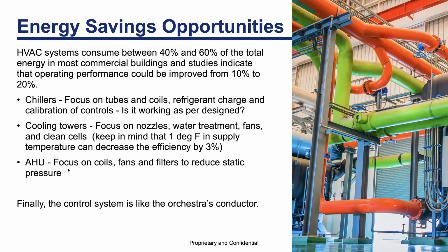For example, sometimes improvements can be made considering a different water temperature set point. And by different, I'm talking about a higher temperature set point, provided that the system, of course, allows us to accept a temperature modification. A system that was designed for 42-degree chilled water, but really and truly does not require 42. Instead, we can analyze how the system would perform if the set point temperature is increased from 42 to 43 or even 44 degrees. So that's a potential evaluation that we can determine right there.